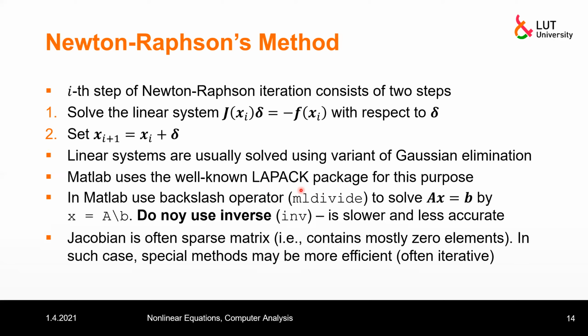So, how to solve it in MATLAB? The best way is to use the backslash operator. It's called mldivide. So to solve Ax equal to b, you must write something like that: x is equal to A backslash b. Of course, there is always the possibility to use the inverse function.